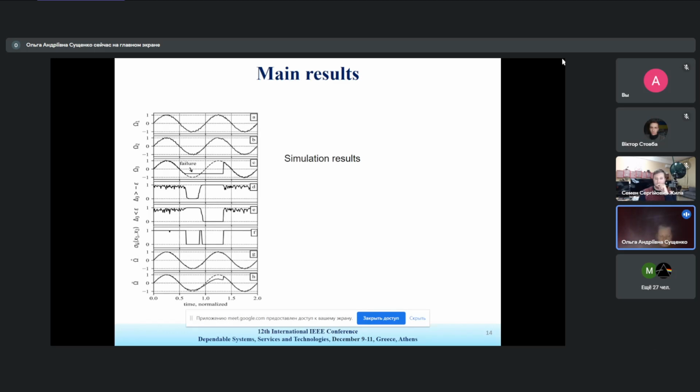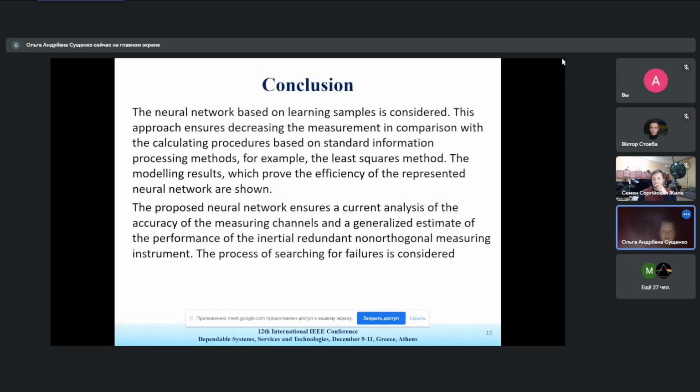The represented redundant instrument with the proposed neural network realizes the quorum element. The first layer of the neural network implements information about deviation of the gyroscope measurements from the weighted average value, figures D, E. Weighting coefficients are formed by the second layer of the neural network, figure F. The transformation matrix is created by the weighting coefficients of sensors.